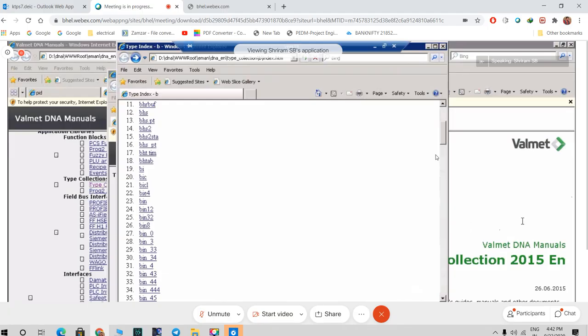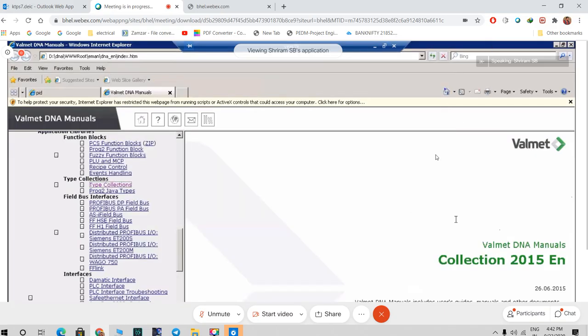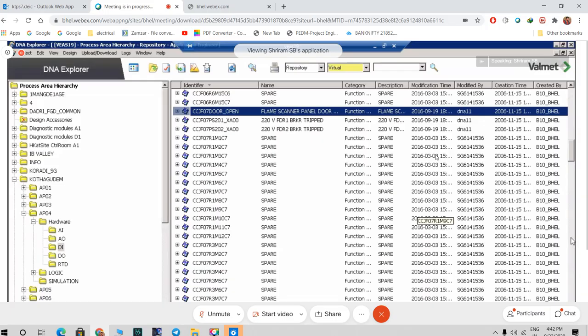Can we tune the PID control block of a particular valve virtually, and after getting satisfied virtually we can download to real? Actually in sites we don't have any virtual simulation. I don't think virtual simulation is possible, but there is a utility which we call the PID auto tuner. That will depend upon what kind of software you opted for in your contract. If the PID auto tuner is there, it will try to auto tune your PID and show the control diagram, and once you are satisfied, you can test it. So that is one way of checking this PID without downloading to real. But it depends upon the option of contract.